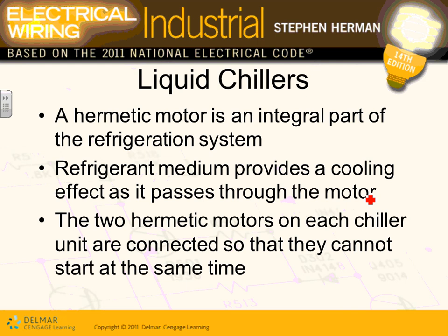Now the chillers, instead of chilling refrigerant, they chill water. They have two refrigeration cycles. One cycle, the refrigerant will chill the water and circulate the water to the air handling unit. They blow the air right through a coil that has cold water, and then from the other end you get cold air. That's what the chillers do. So the job of the chiller is to chill the water, make the temperature of the water lower.